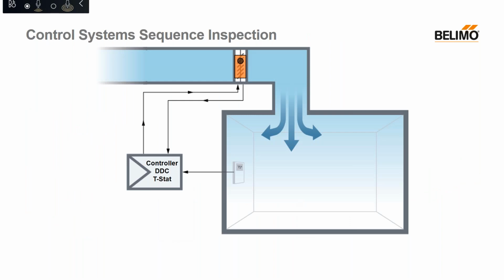The next step in the guidelines was to review your sequence of operation. Going through and reviewing each step will be beneficial in helping with maximizing performance and possibly having the benefit of creating or upgrading a new sequence for improved ventilation. Here, what you see is a basic sequence in which we'll run through all the different steps. The first step is the room sensor feedback to the controller. It will be important to make sure you are getting an accurate temperature feedback to the controller.